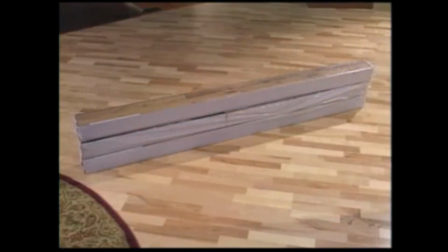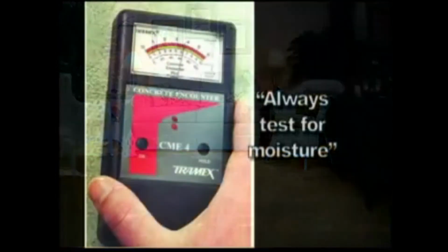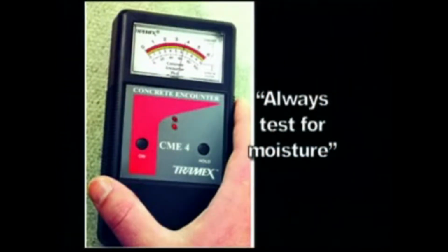The final adjustment required for proper installation is to acclimate the wood to the temperature and humidity levels of the job site. This requires a minimum of 48 to 72 hours in a climate-controlled area. The substrate must be within 4% of the current moisture level of the wood. Not following this basic rule will undermine everything the wood has undergone by man and nature. Always test for moisture.